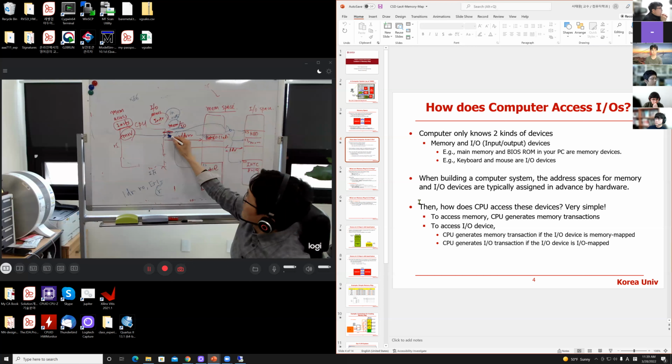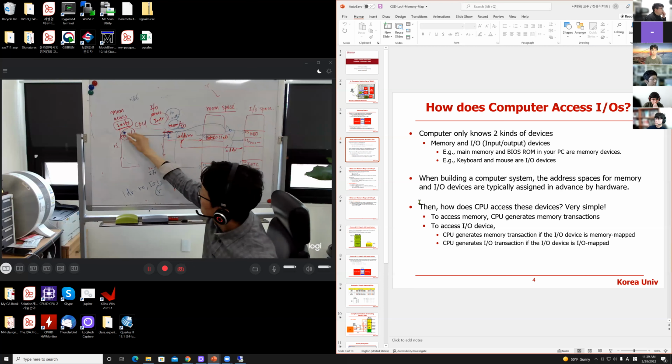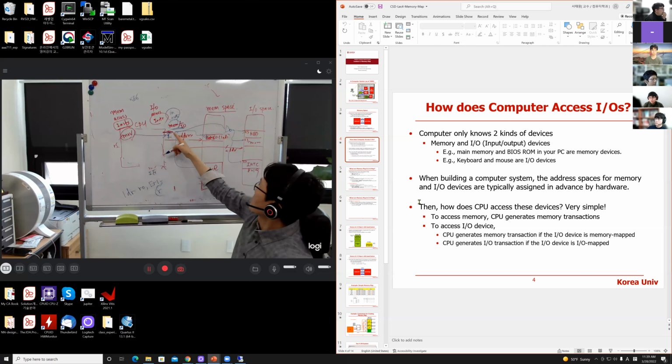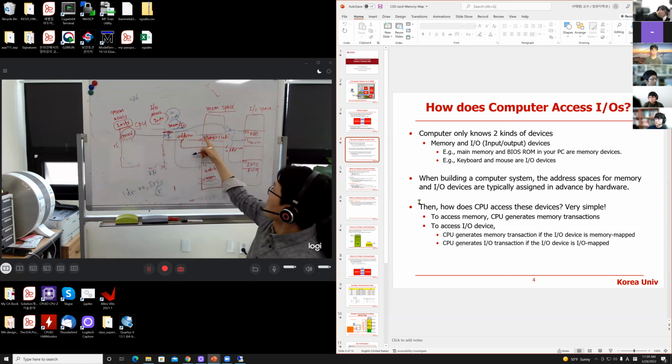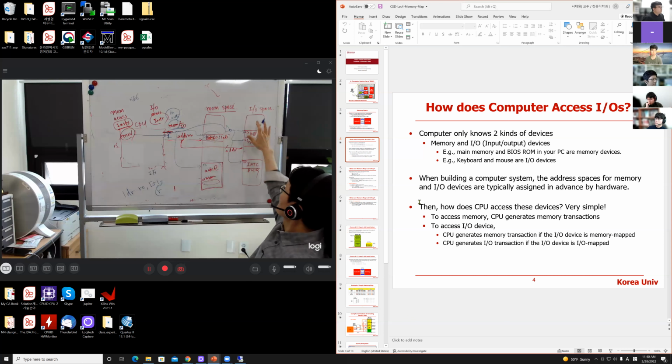When the CPU executes a move instruction, then 1 is connected to here, which means that chip select is selected. That is the memory hardware component in memory space. Through the inverter it becomes 0, so those devices are not selected.